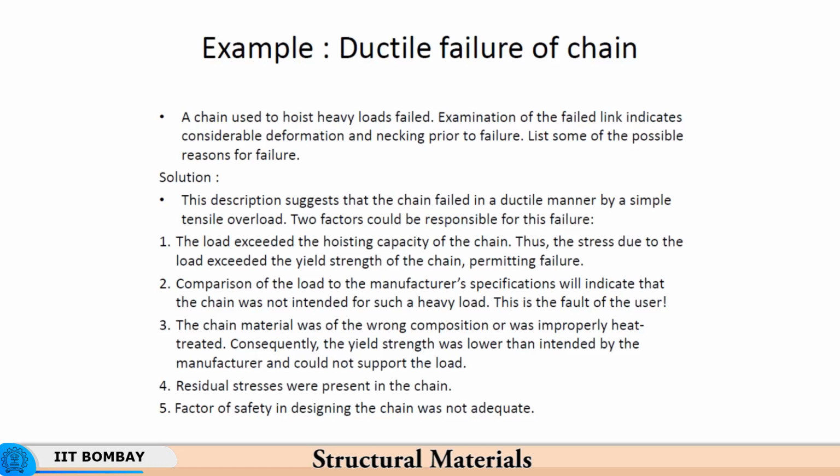So, residual stresses are the stresses which are applied to the chain link even before any load has been put on it. So, let us say the chain is rated for 1000 kilonewtons, and your residual stresses are to the extent of 200 kilonewtons, right. Then what happens? You know that the chain is rated for 1000 kilonewtons, but already there is an internal load due to elastic stresses to the extent of 200 kilonewtons. So, the minute you go beyond 800 kilonewtons, the chain will snap.